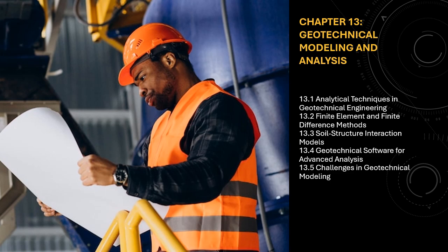13.1.1.2 Settlement analysis. Closed-form equations such as those derived from elastic theory or from the work of Terzaghi and Peck are used to estimate the settlement of shallow foundations. These solutions assume a linear elastic behavior of the soil and help calculate the immediate settlement and consolidation settlement for foundations subjected to vertical loads.